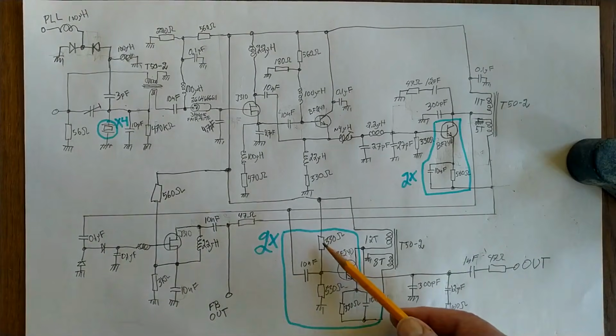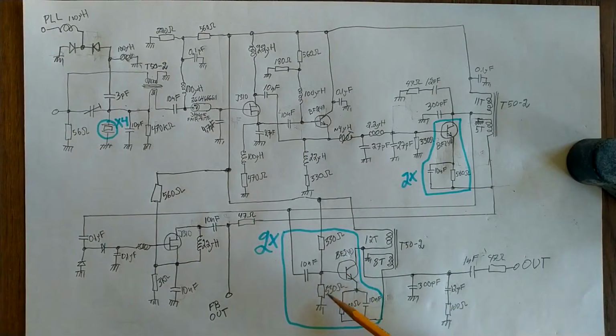The transistors have independent bias voltages because the noise generated by the resistors should be uncorrelated for the 2 transistors. So that was an old thing from long ago. I didn't change it because it does no harm, but I don't think it is necessary.